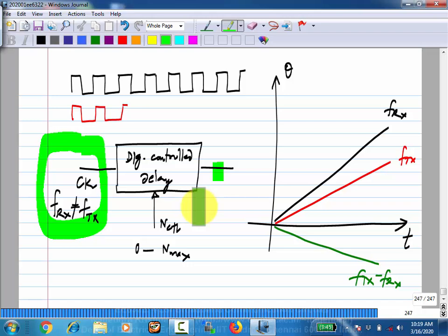That's all, right? So you can see basically you can make the cycles longer by having some delay for this rising edge, larger delay for the next rising edge, larger delay for the further next rising edge, and so on. So you have to keep going like that. Is this okay? So like this, you can generate a different frequency. It's very obvious from the phase picture. The phase difference between two signals of different frequencies is the ramp. So if you give a ramp control voltage to this, the output will be a signal of a different frequency. Is this okay?